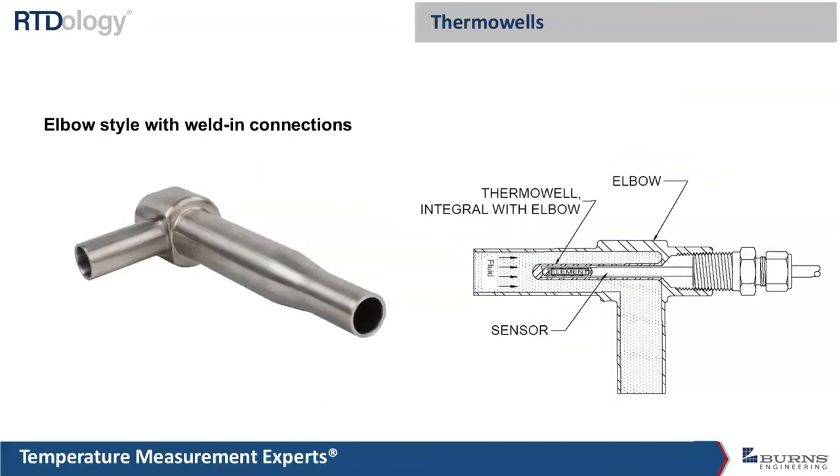Another style of sanitary well that's fairly specialized is what we call an elbow style. These will typically be used for very small diameter lines, maybe 1/2 inch up to about 3-inch diameter. And they work really well for that because the probe can be installed in the run of the pipe here, so you can get sufficient immersion length to get a good, accurate measurement.